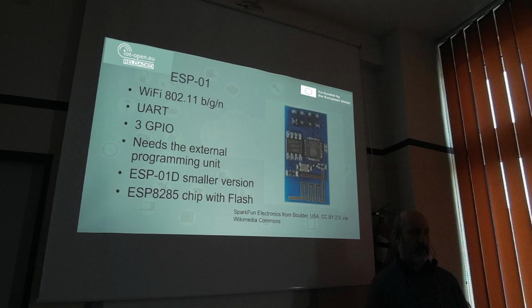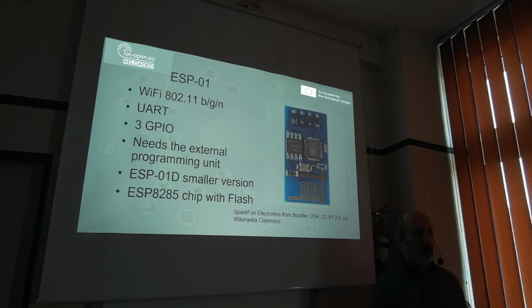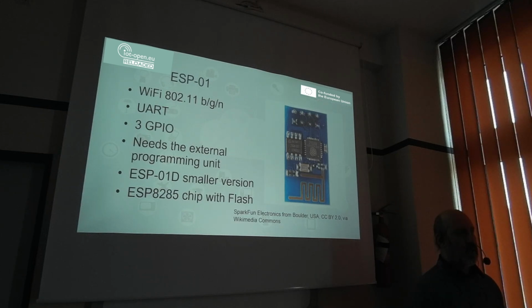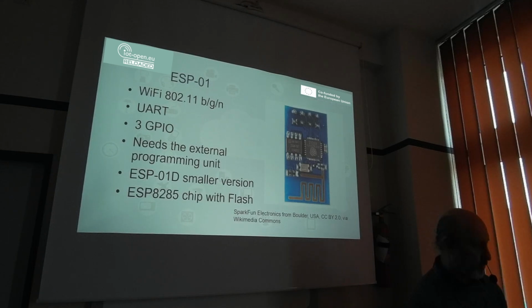It was the basis of some interesting boards. So the boards I show now are all based on this ESP8266. So the overall functionality is the same. The difference is the number of pins and the possibility of programming, or the necessity of using an external programming module. So for example, ESP01 has just 3 GPIO pins.